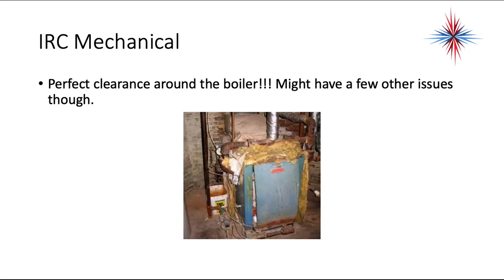Okay. Boilers have to have room all the way around. Now, this boiler has a few other problems, but it has enough clearance around it so you can work on all sides of the appliance.